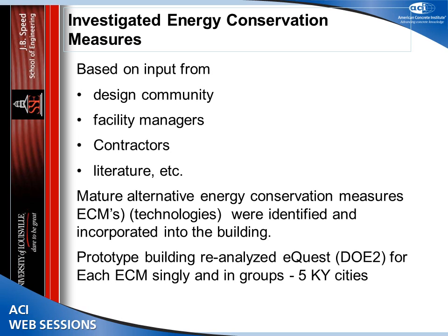And we identified a series of mature alternative energy conservation measures, or ECMs, that would typically at least be considered for school designs in the Kentucky area. We then individually incorporated each of these ECMs into the building model and ran an energy analysis over a year's period of time for all 5 of the Kentucky cities.